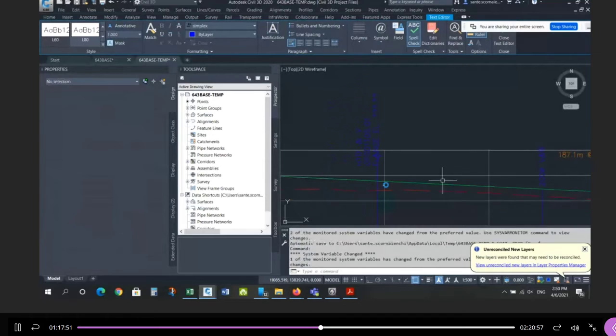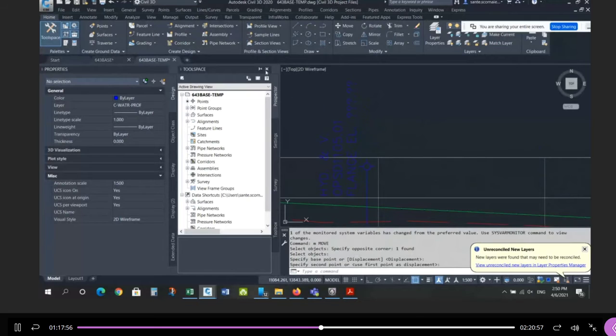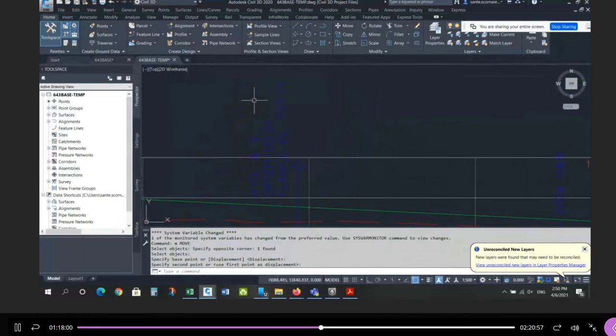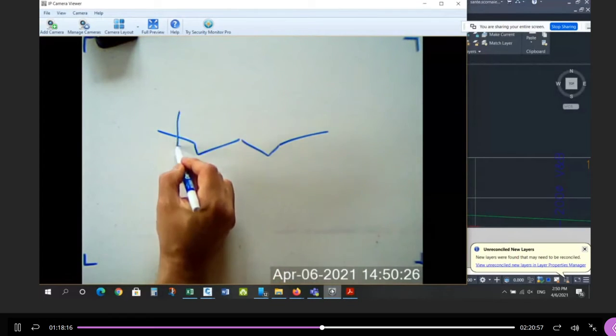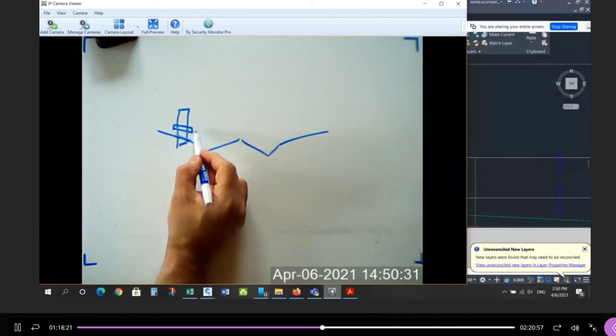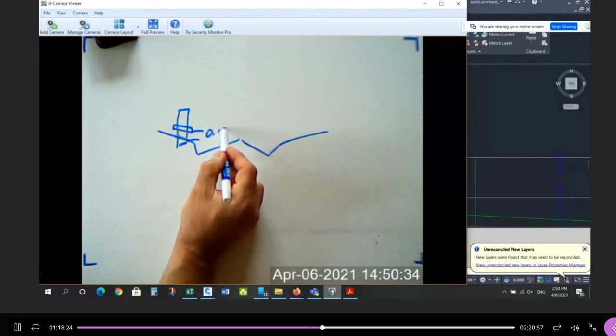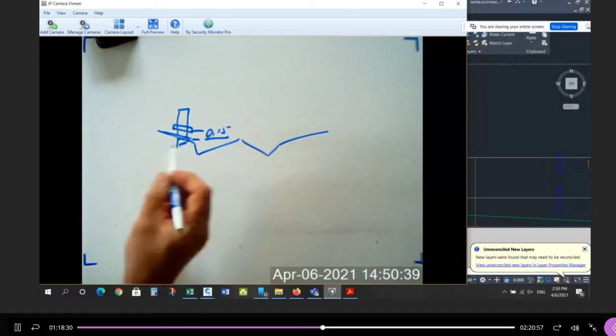And you need to know what that number is. I'll show you how to get it. Right? What's the flange elevation? The flange elevation, if you read the standard in Halton, the flange elevation in Halton is the boulevard elevation, wherever the hydrant is, plus 0.15. Okay, so here's what it looks like in cross section. Right? So if this is your cross section of the road, where the hydrant sits, this is the boulevard elevation. The flange for the hydrant is 6 inches above the finished ground, 0.15 above. Okay, so whatever the elevation is where the hydrant is on the boulevard, add 0.15.